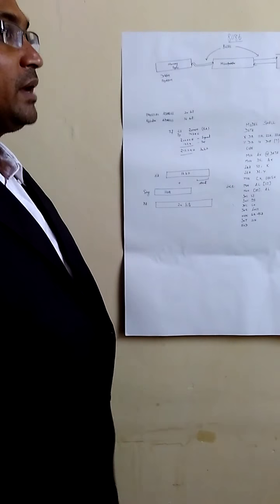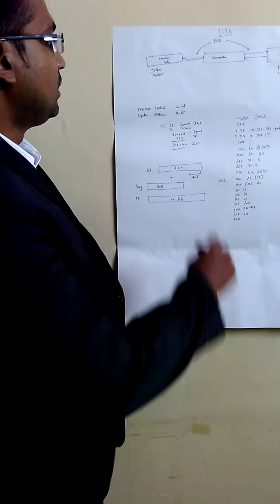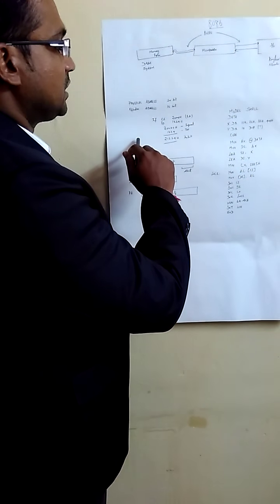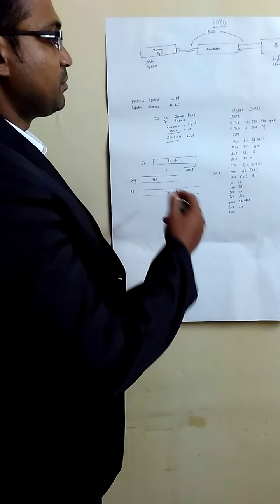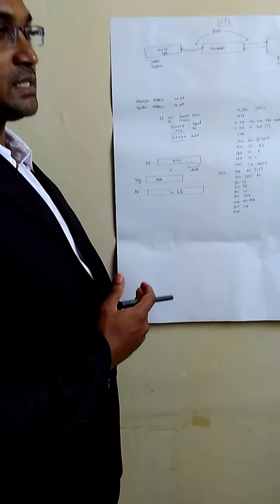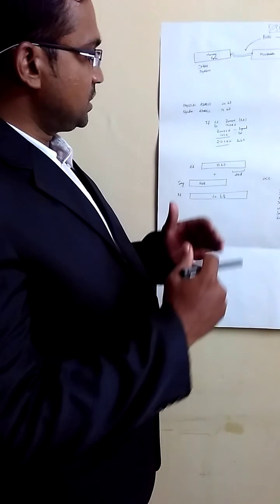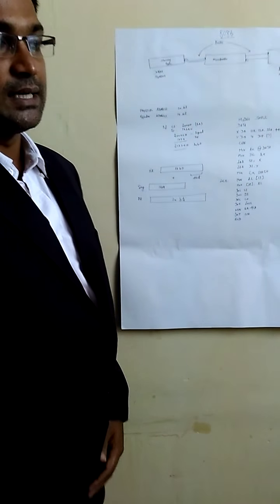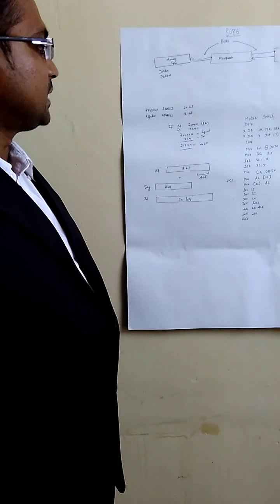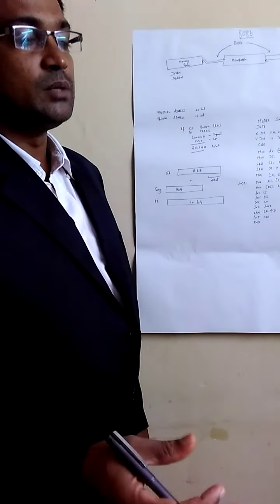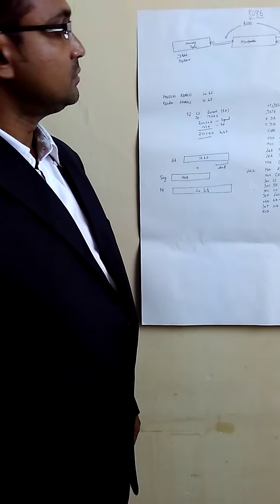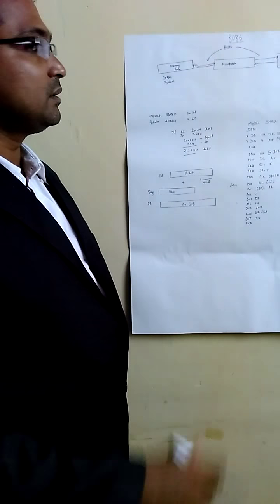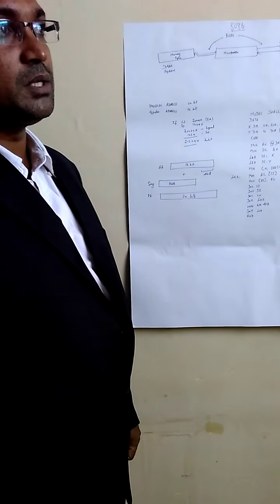20 pins are mapped to the 20-bit address A0 to A19, whereas the effective address is the segment register's address. We have seen CS, DS, SS, ES. The 16-bit address is taken from any of the segment registers, and it is shifted towards the left hand side, and if we add the shifted value to the instruction pointer offset, you can get the 20-bit address. This 20-bit address is going to be visible for our knowledge. Using that knowledge we can locate the program's running place, execution place.